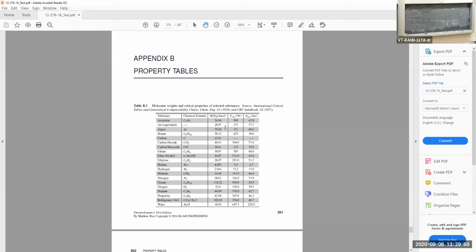Now for the units to work out, this megapascal has to be expressed in terms of kilopascal, so it cancels out with the kilojoule in the gas constant. So let me convert out of the mega. There's 1,000 kPa per 1 megapascal, and the megapascals will cancel out. Let's put that all in the calculator and see what the mass is.